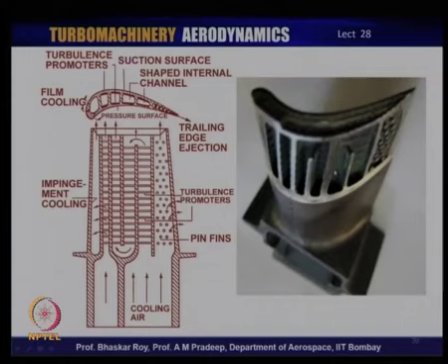So, that is the kind of passage that typically turbine blades have, and then the air finally comes out through the tips over here, which also does a little bit of tip cooling. The tips need to be cooled also, along with the cross flow over the tip. So, it is an elaborate cooling technology that is often used in modern hot gas blades. This was a stator blade.